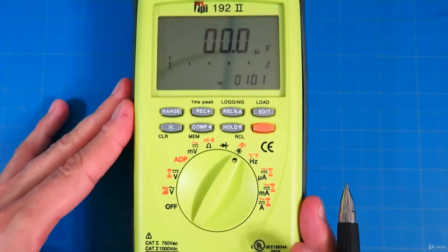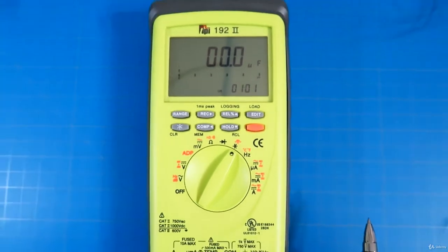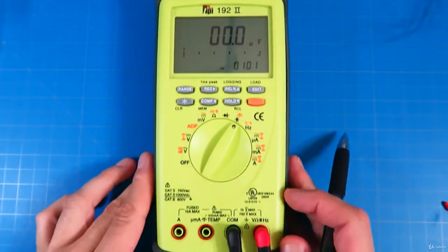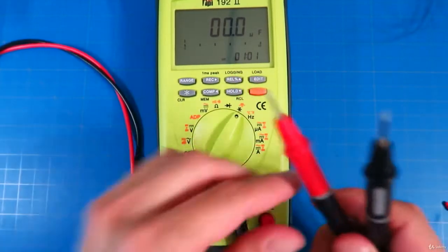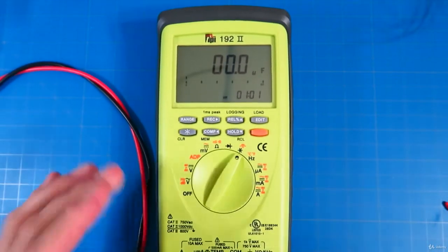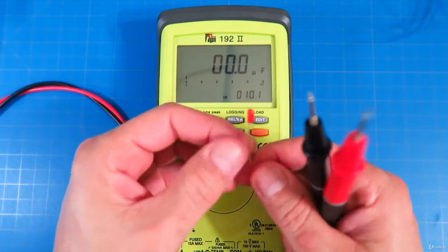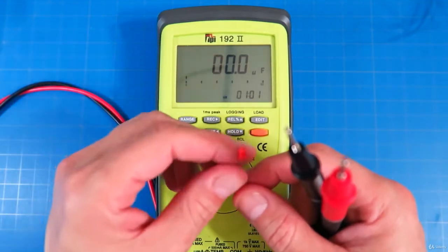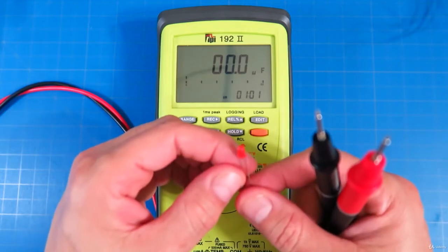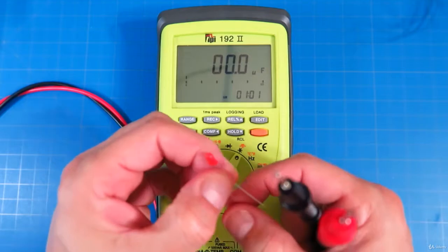Okay. And then let's just back out a second so you can make sure you're seeing everything here. The leads are just in here, and we're just going to grab these leads. All right, and here are our leads. We're going to come back here so you can see the screen a little bit better, and we're going to take our capacitor here. Now, when we're measuring this, if it's a polarized capacitor, we want to measure it in the correct way. I can see that the lead on the right is the positive lead, so I'm going to bend those out.